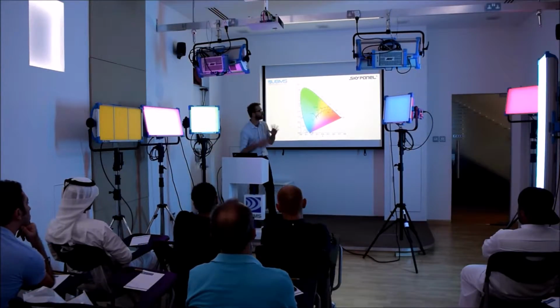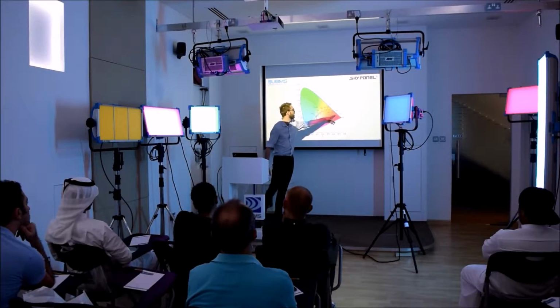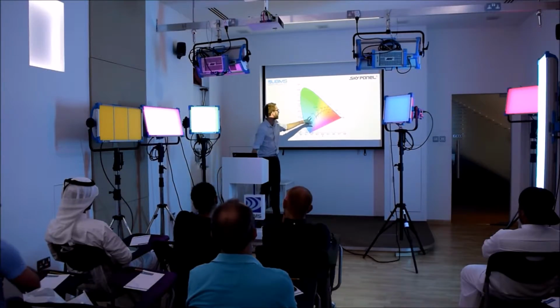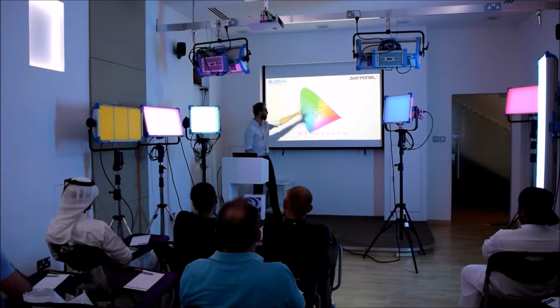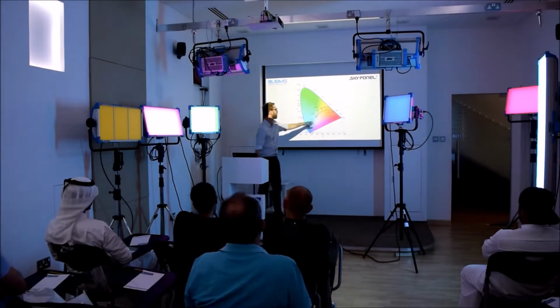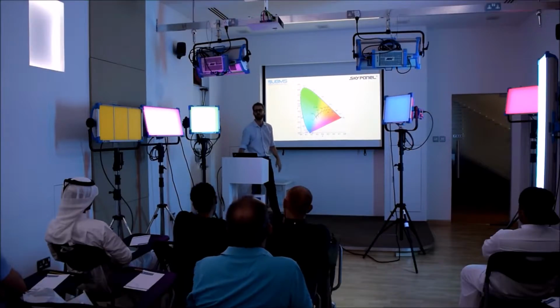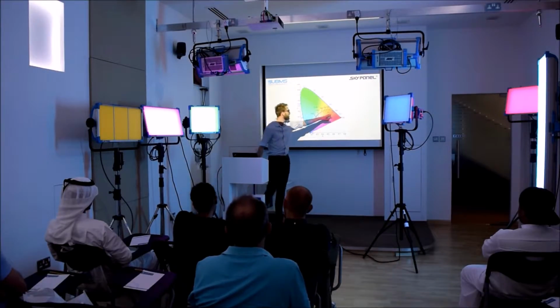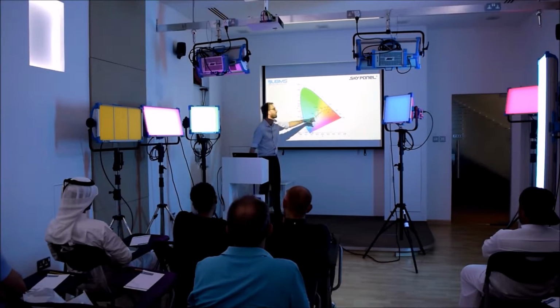And if we are to plot a line which represents our Kelvin color temperature, this is what the line looks like. So when it's put on a full chromaticity graph, including all of the other colors, this line basically represents our standard Kelvin color temperature that we all talk about when we look at lighting. So degrees Kelvin are marked here, so 1500 to 2000 to 2500 all the way up to 10,000.